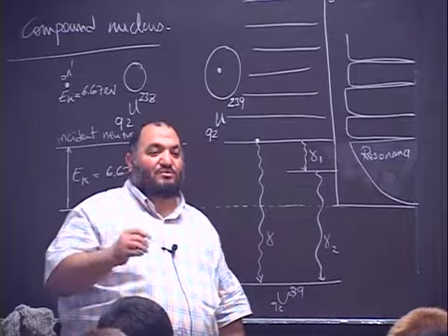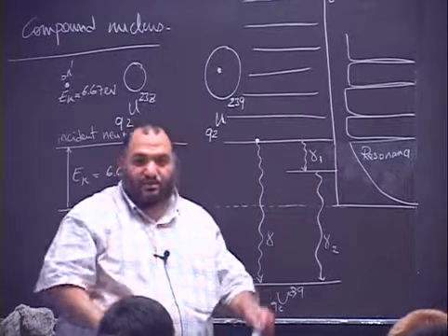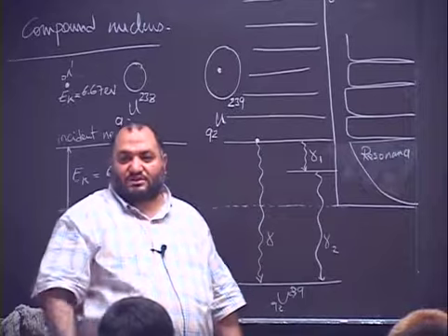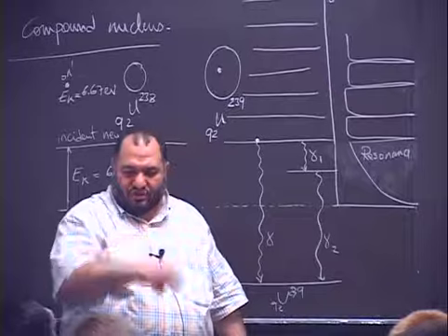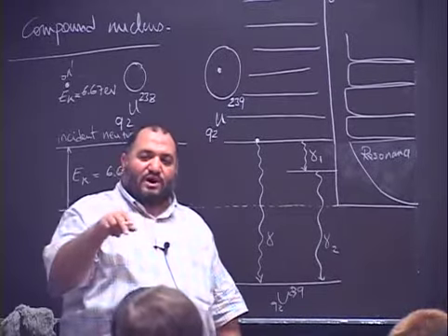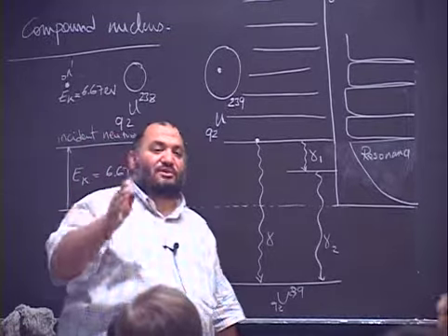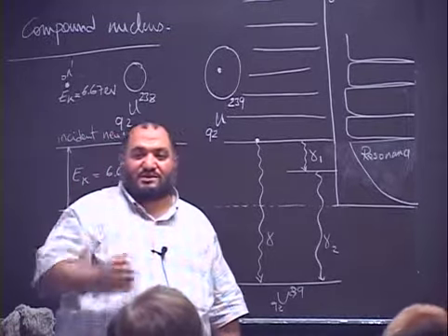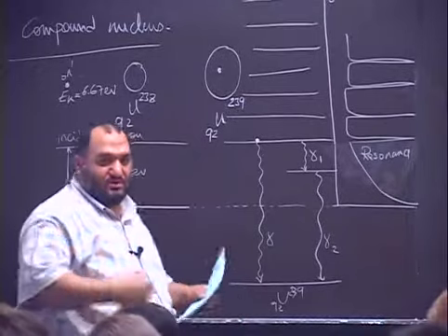In this case, the circuit is called a resonance circuit. If you change the frequency, you will come to the point where XL cancels XC, and you are remaining only with the resistance, and you have a maximum current flowing into your circuit. This is called resonance.